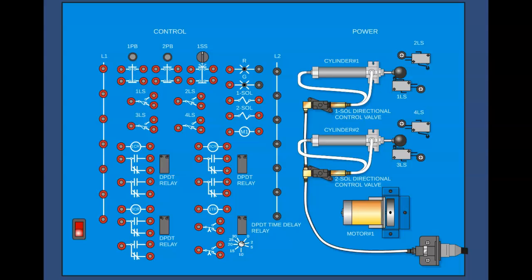So now we're going to visit relay contacts. And remember, relays are electrically controlled switches, and we use those for a variety of reasons: for mixed mode voltages, for higher currents that we can control with lower currents, for the very fact that we can know the status of the relay, whether it's energized or de-energized, by using either the normally open or normally closed relay contacts. So there's bunches and bunches of reasons that we use relays.